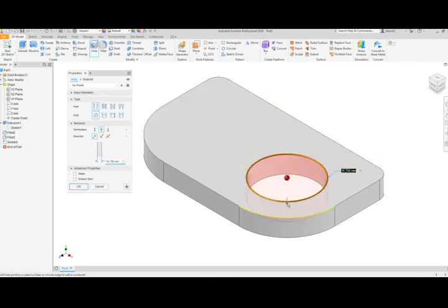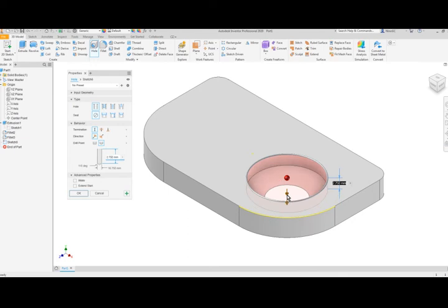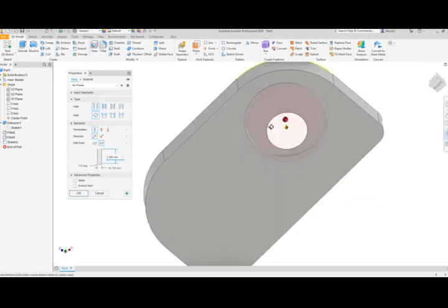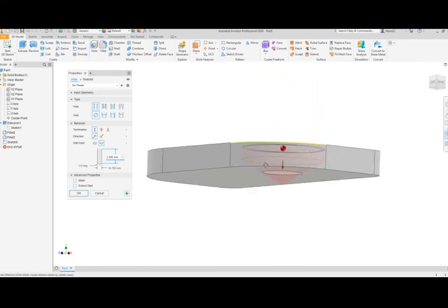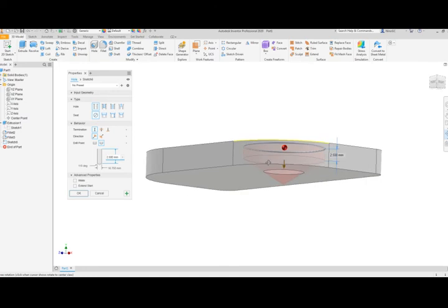And also the arrow, which is shown right here, I can indicate how far I want it to actually drill through. So if I want it to drill through only to about 2.5 millimeters, we know that the plate is 5 millimeters. It is going to drill through to 2.5. However, as you can see, it also will poke through the opposite side of the plate. This is due to the fact that the drill point is being used.